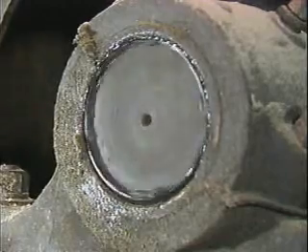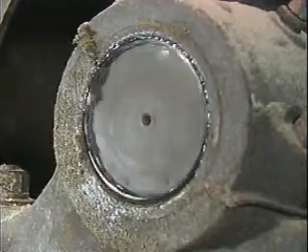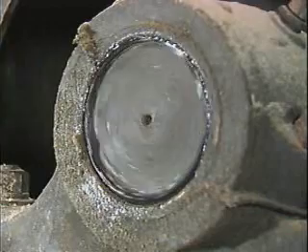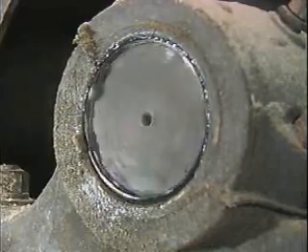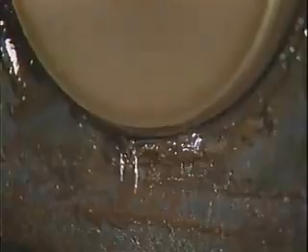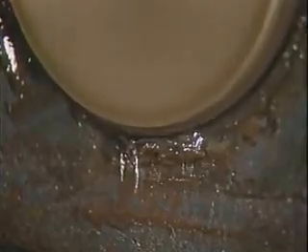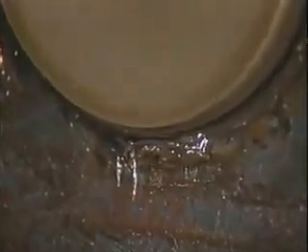If the grease in a bearing breaks down from the heat that's generated during operation, the grease will leak out and leave the bearing dry, causing the bearing to seize. A stable grease, on the other hand, resists breaking down due to temperature increases or exposure to air, water, or reactive chemicals.